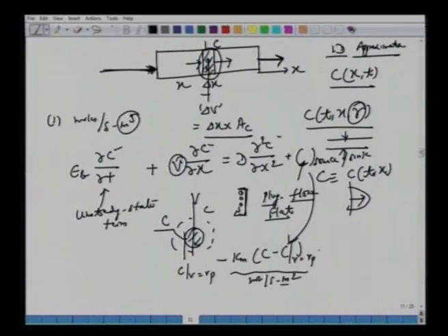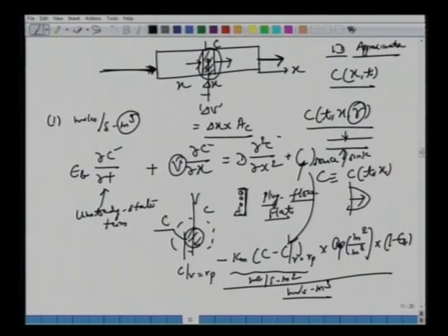All right, that means multiply this by a_p, surface area per cubic meter of particle volume, and then if you multiply it by 1 minus bed porosity, you will get this term as moles per second per cubic meter of your bed volume. So going from particle volume to this bed volume.